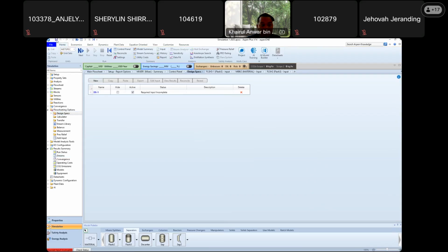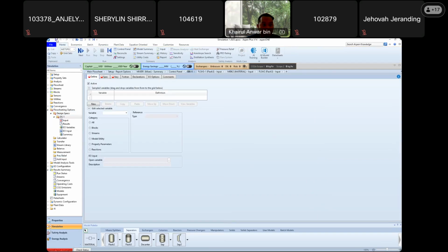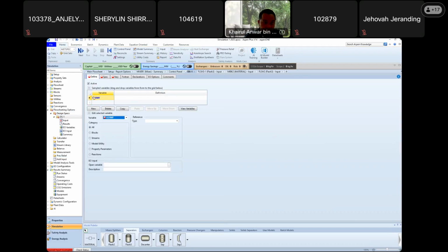Okay. Don't forget to save. Our goal is to get the H2O mass fraction. The variable is H2O MF. Specify it as stream mass fraction.